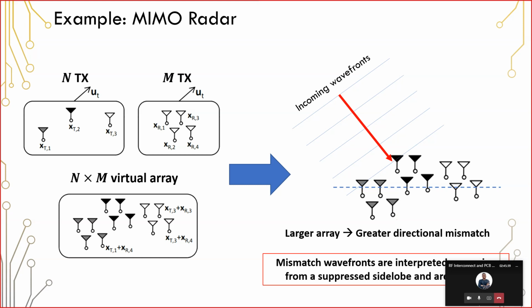Like backup cameras that include a radar sensor or an ultrasonic sensor, they're just telling you that there's an object within the field of view, and that's it. So radar systems that are going to be used for autonomous vehicles need to have much higher resolution. And MIMO is one technique that you can use to get much higher resolution.